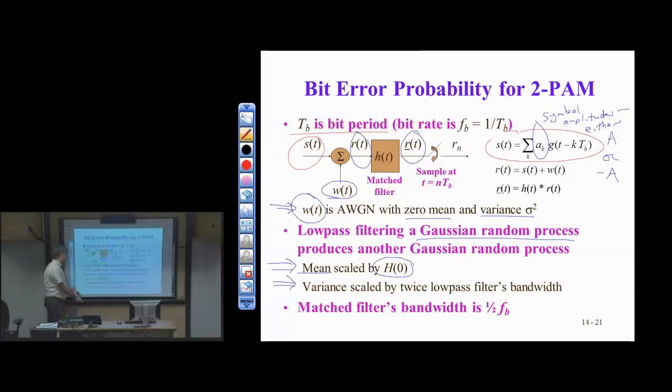Now, if you sit back and think, the matched filter actually has a lot of roles to play. There are actually 3 of them. It's a versatile filter. So the first role of the matched filter is to maximize the SNR at the output of the sampling block. That was part 2's derivation. But there's another role from a signal processing perspective. And what role do you see here in the block diagram? That should look really, really familiar. Filter plus the sampling. So what's the role of the matched filter? It's a low-pass filter.